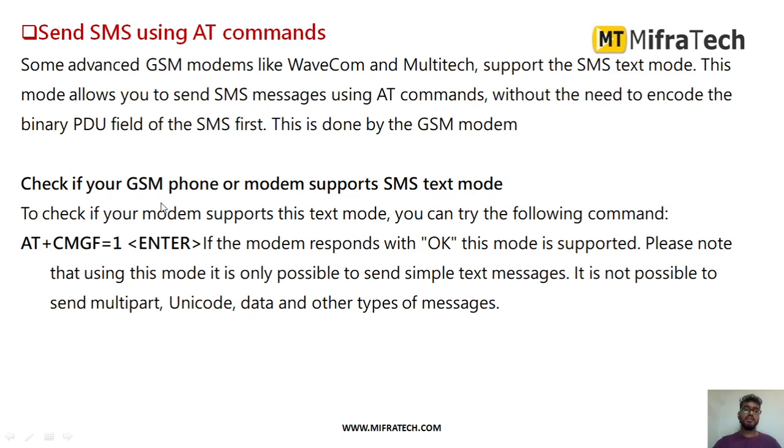First we have to check whether your GSM phone or modem supports text mode or not. For that, you can use the command AT+CMGF=1. After hitting enter, if the modem responds with OK, it means the module supports text mode. You can get to know by that.